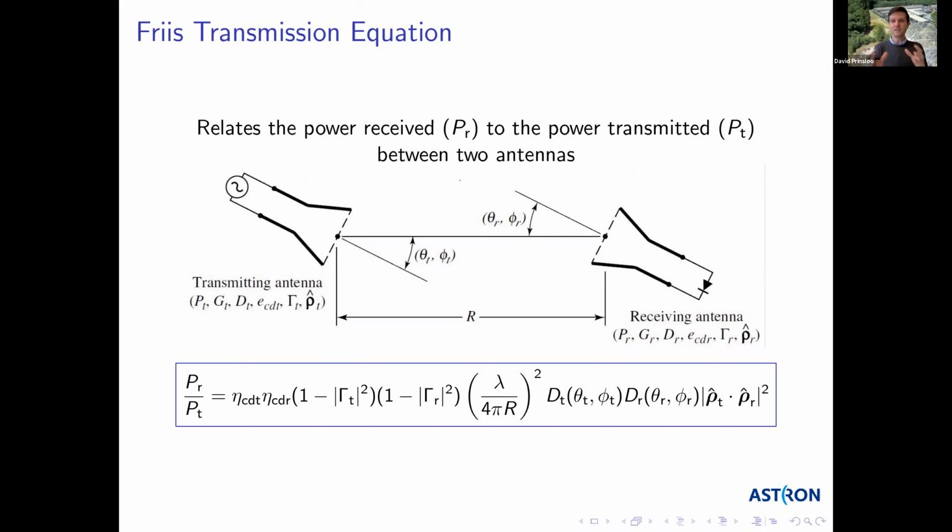And therefore you can use this free space loss factor, assuming that. A completely different set of measurement expressions apply when you're trying to characterize antennas in the near field. You can measure the near field, but then you'd have to apply a Fourier transform to the near field distribution to get to the far field. So I'm not 100% sure whether the radial distance applies. I would say in this instance, this assumes definitely the far field. That's the safest answer I can give you at this moment.